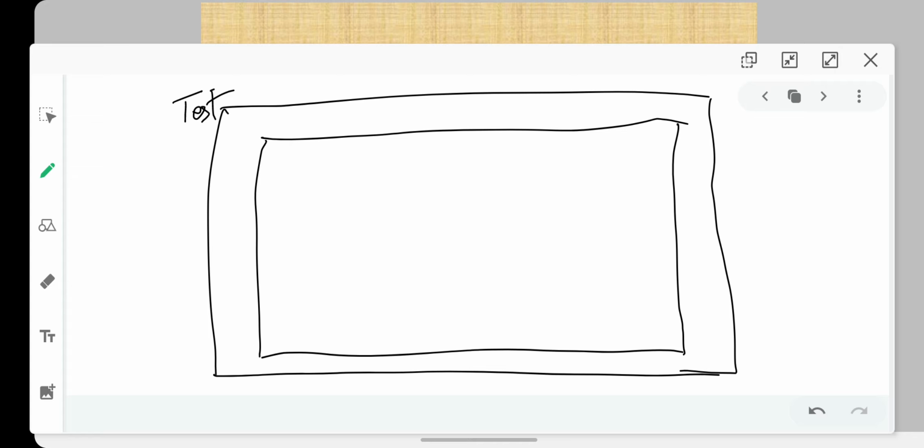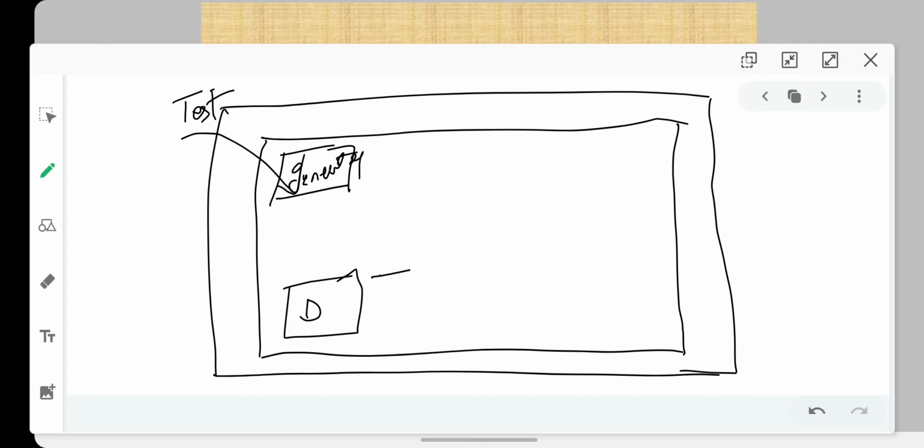The test case provides the required data that is going to be driven to the DUT, or the design. So we have a generator. When you drive the test case onto your generator, it is going to generate all the required values, and then you have a driver here, and we have a monitor.